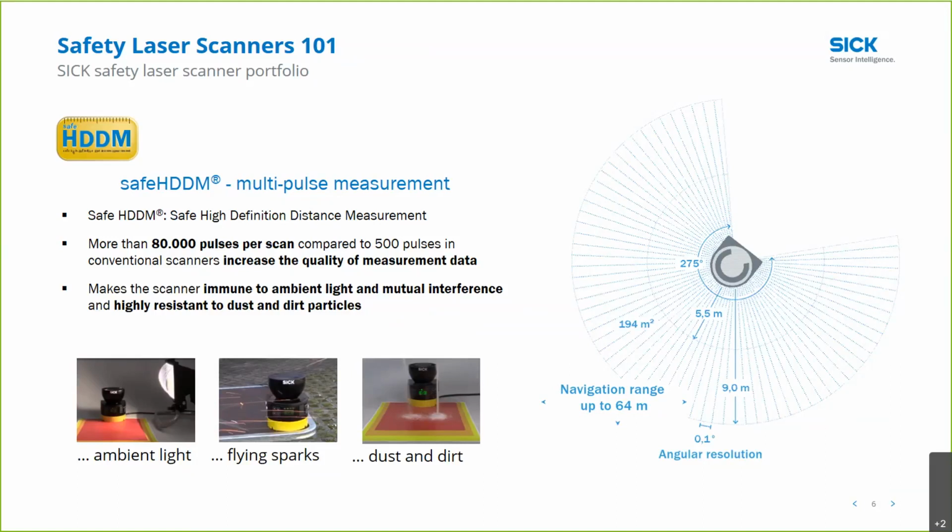Let's see, we've got a few more here. Let's pick one. This is another one from Katie. Let's say you've got an AGV, an automated guided vehicle, with a scanner on the top of it and a couple at the bottom. Can you set the sampling rates individually for each of those scanners? Yep, absolutely. Every scanner can have its own multiple sampling rate set.